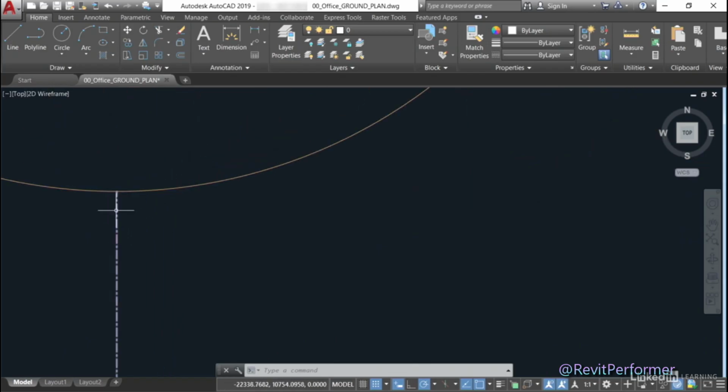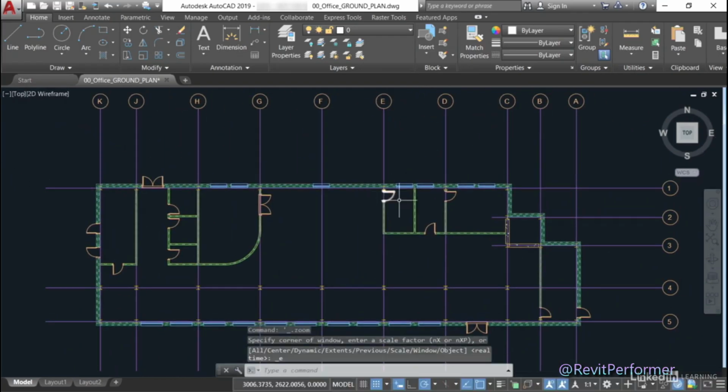You can see the spaces and the dashes and so on. I'll double click on the wheel again to zoom extents. Now, what that means is that basically these particular grid lines are using a line type scale that is a little bit too small. We want it to be bigger so that they stand out. So what we would do then normally is make sure that our global line type scale in this particular drawing is set accordingly.